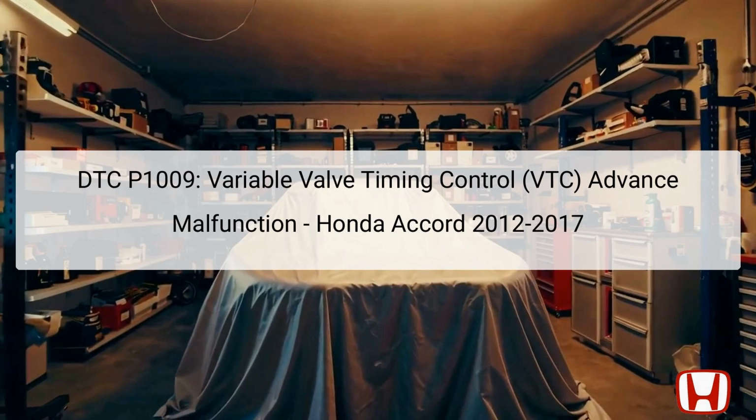Welcome to the diagnostic presentation on DTC P1009, which indicates a variable valve timing control, VTC advanced malfunction specific to the Honda Accord models from 2012 to 2017. This error relates primarily to the operation of the intake camshaft's phase adjustment mechanism, essential for optimizing engine performance under varying driving conditions. The VTC system uses oil pressure to actuate the timing, which means it adjusts the camshaft angle for improved efficiency and power delivery.